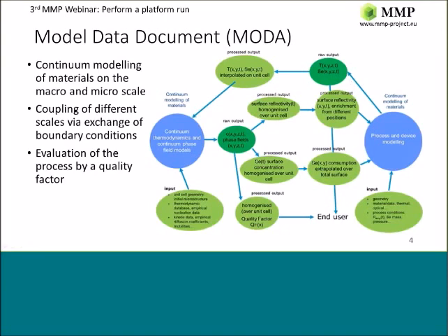So it's a temperature profile which comes from the macro simulation, and that serves as a boundary condition for microstructure evolution. From the statistics over several points in the macro field, an evaluation of the microstructure is done, and the concentrations or phase fractions are given back and are mapped by experimental data tables back to a measurement of the emissivity, which serves as a boundary input back for the macro simulation level.